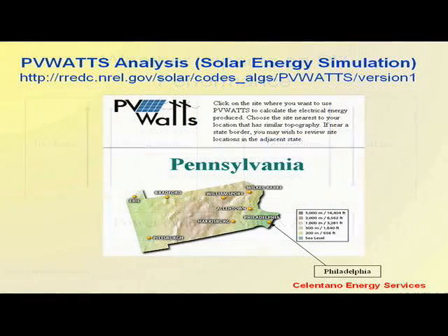Okay, here's a nice website you can go to, and you can plug in some information. You can find your latitude and your longitude. You can plug in your azimuth for whatever roof you're planning on putting something on, and this website will do the calculations for you, and you can tell how much insolation you're going to have at that location.